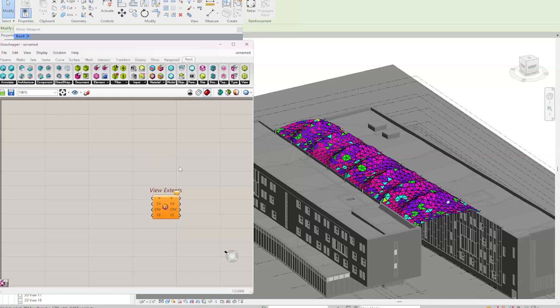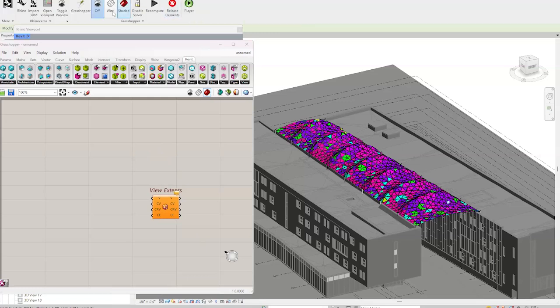Another question in that vein, Daniel's asking, is it good practice to implement geometry into Revit without Grasshopper? So presumably taking Rhino geometry, bringing it into Revit without using Grasshopper, and in such case, where in Rhino do you link the Revit data? Yeah, Japhy's showing off right now that you can directly import a 3DM, which is the native Rhino file, into the active Revit model or family.